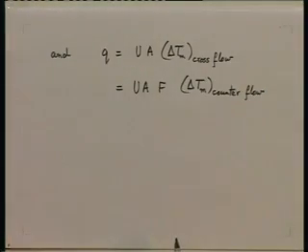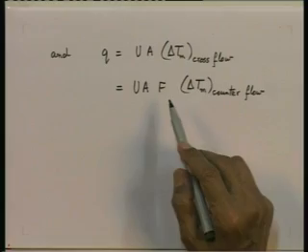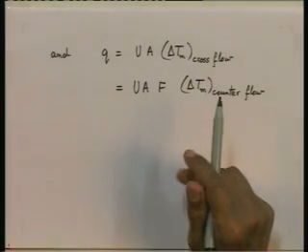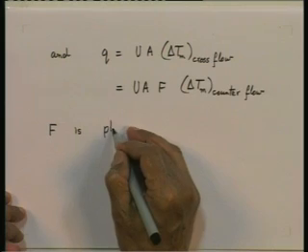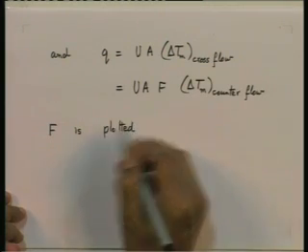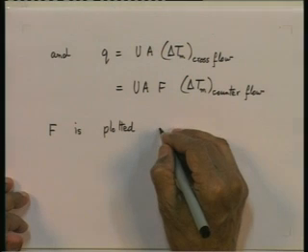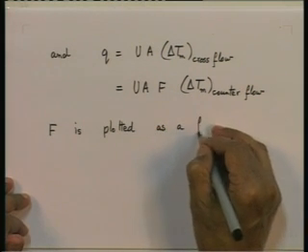So, when we have a cross flow problem, a situation of cross flow, we will calculate the delta Tm in counter flow, get f which has been obtained by numerical integration, which I will tell you shortly how we get it from the various charts or graphs available, and substitute into this as our basic performance equation. Now, the quantity f, how do we get it? F is based on the numerical integrations, f is plotted as a function